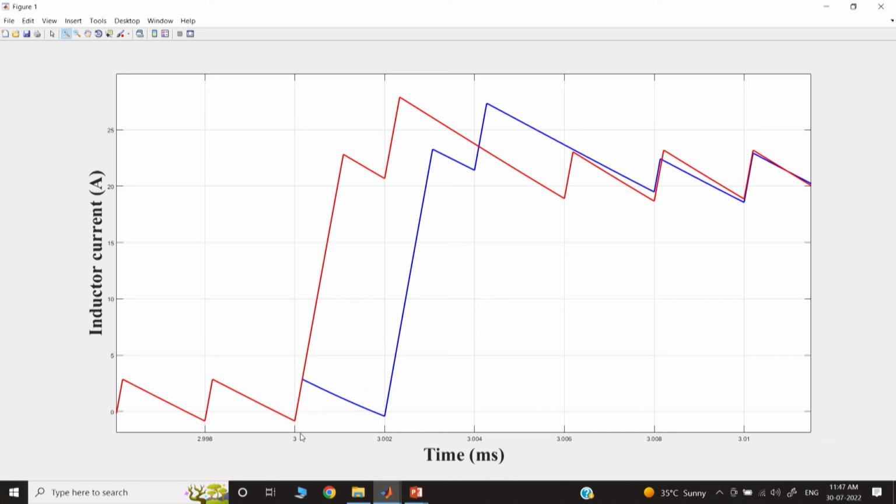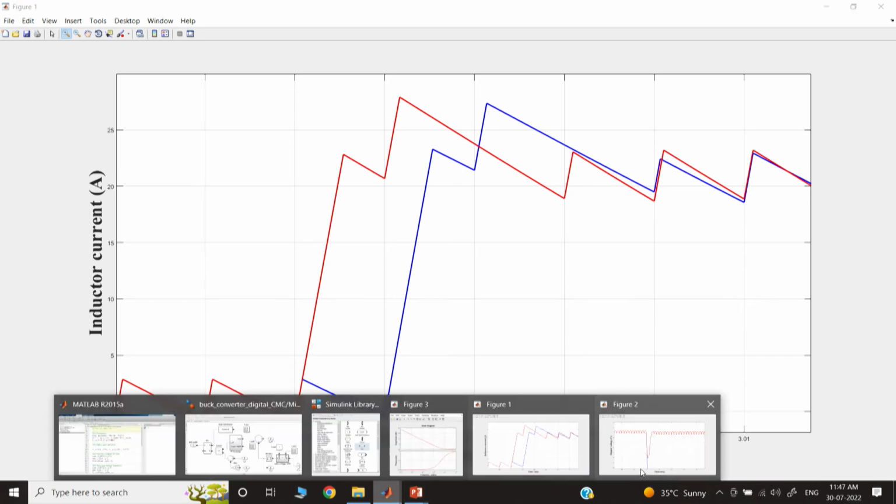So, this is because we have applied a load step at the point of switching, and the sample for that signal was captured here. So, it did not recognize the delay. That means it was showing almost one full cycle delay. The inductor current has not responded to the transient. So, the transient is applied here, but the sample is captured somewhere at this point. So, after sampling, the peak current does not know that there is a transient here. It is almost like a one cycle delay, and that is why you will get an additional undershoot.